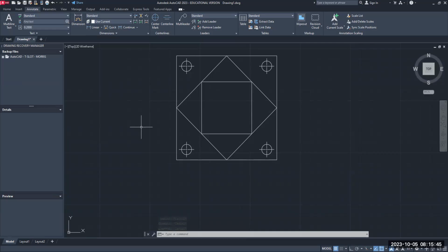All right, so I like that. That's good. Now I'm going to create a bisector. If you go up here right beside the center mark, you see center line. Click on center line, watch, and then click on this line, and then this line. Notice it puts a center mark, which is the midpoint between these two lines. I'm going to repeat that again. Click on the center line, click on this line and this line, and hit escape a couple times.